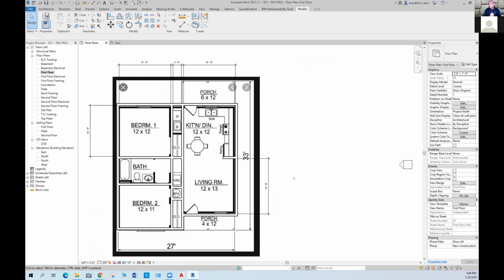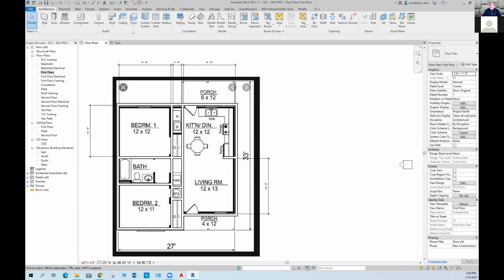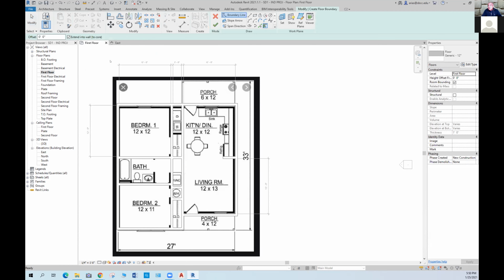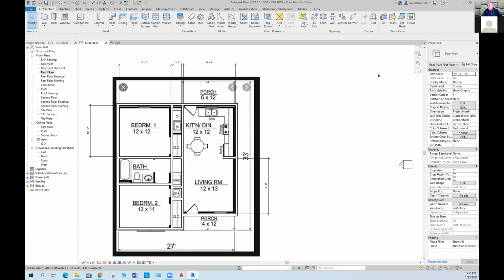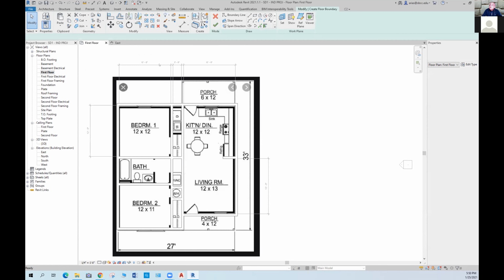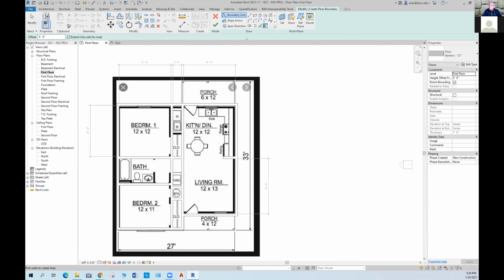And now I continue. So what's the workflow like in Revit? Well, remember, I did the walls first, and now I can do the floor. And so I'm going to do architecture and floor. Floor architectural. The same thing here. Once the tool is selected, then I can select the type of the floor. Once again, architecture, floor, floor architecture, options bar comes up.